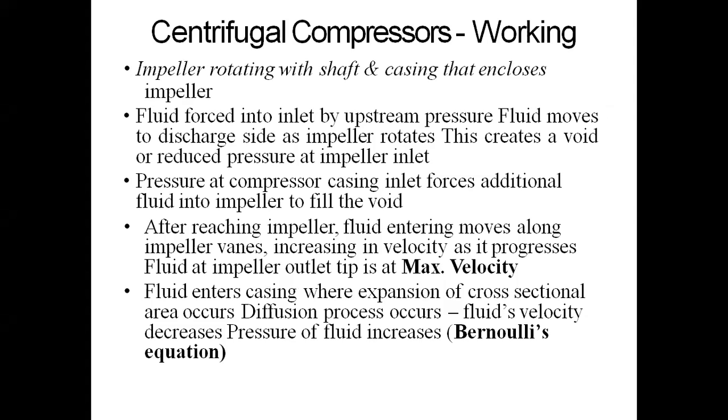Centrifugal compressor working: an impeller rotates with the shaft inside a casing that encloses it. Fluid is forced into the inlet by upstream pressure and moves to the discharge side as the impeller rotates.